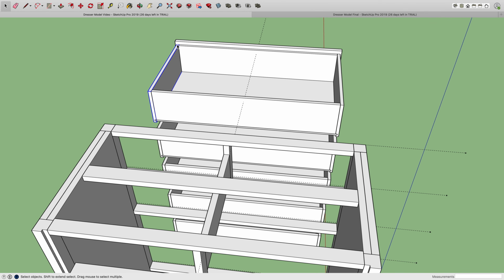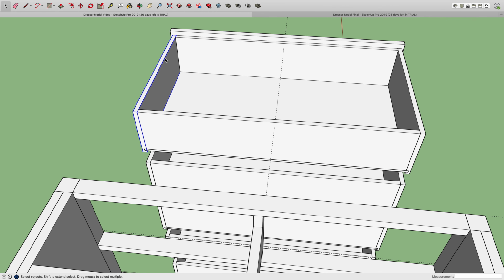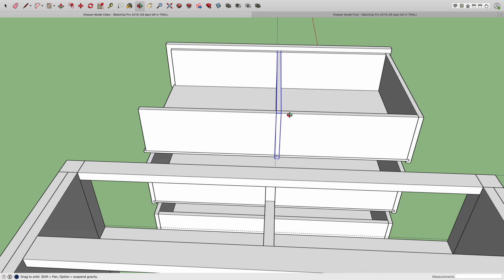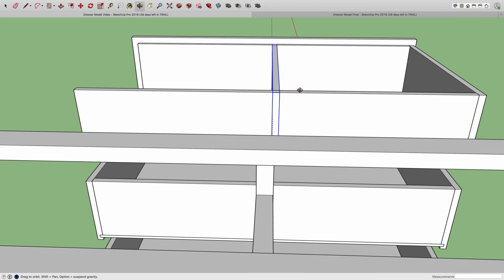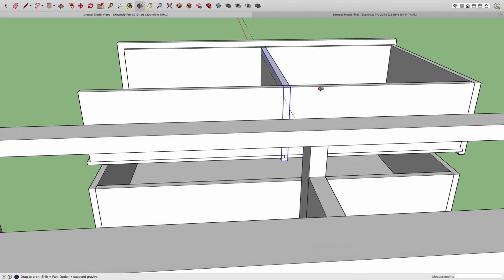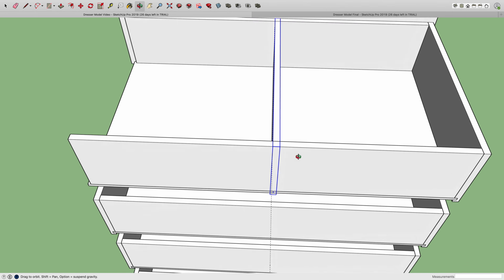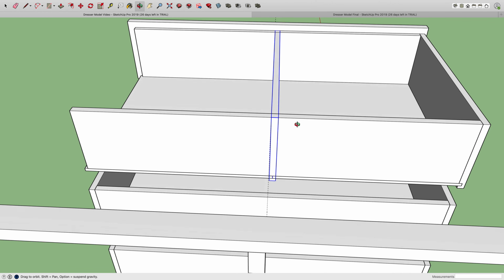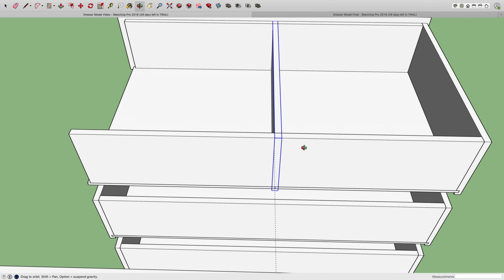So first, let's just move it right onto there. We'll grab the move tool, we'll grab this point right here, I guess will work. And we're going to slide along green, and we're going to click it right on that midpoint right there, where that line, I suppose, runs. You can see that line's running down through there. And next, we can move it over 1/4 inch.